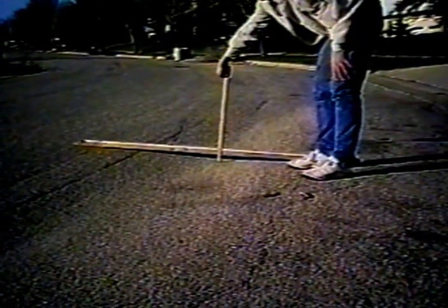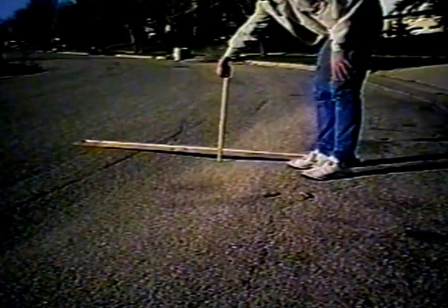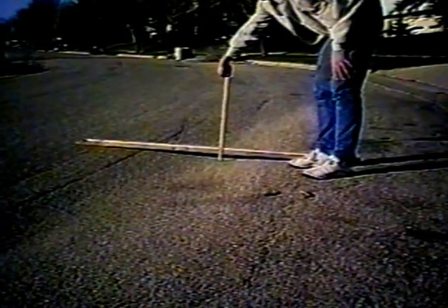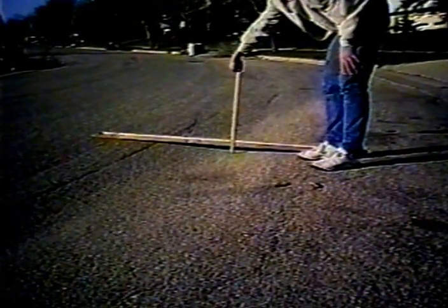If you have deep rutting, that is rutting that you can measure in the number of inches, then that's probably an indication of problems deeper down in the pavement. That is, inadequate base course or inadequate subgrades, poor drainage, all combining to cause rather severe rutting. I guess a general rule of thumb you can use is that the depth of the rutting in the surface of the pavement can help you indicate where the problems are in the pavement. Shallow rutting, generally speaking, would be up in the surface of the pavement. Deep rutting is an indicator of problems deep down in the pavement that will usually require complete reconstruction of the pavement itself.